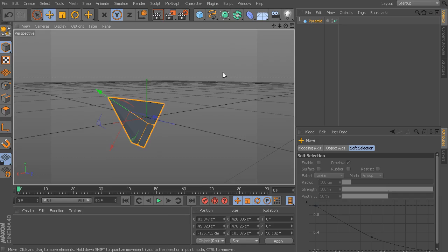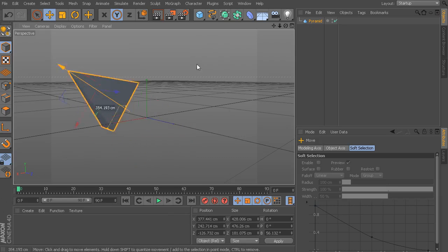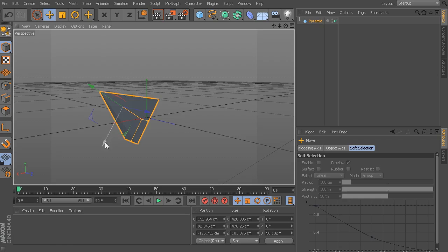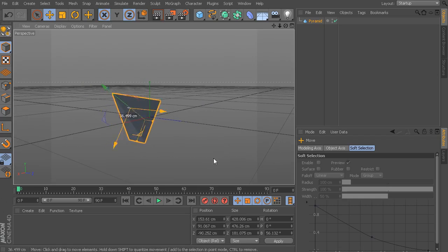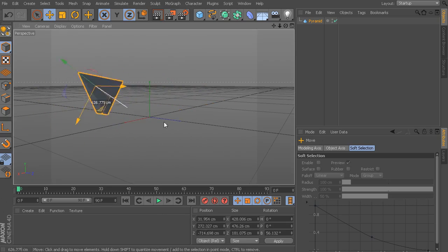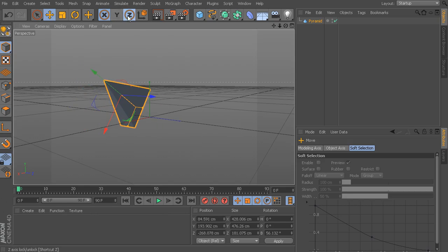And now, again, if I click and drag anywhere outside the manipulators, you can see it's only going to move it along the y-axis. If I, let's say, maybe only wanted it to move along the Z and X axes, I could turn both of those on, click and drag. You can see now it's moving it along the X and the Z axes, but it's leaving the Y axis alone. So that's sort of what these little locks up here do.